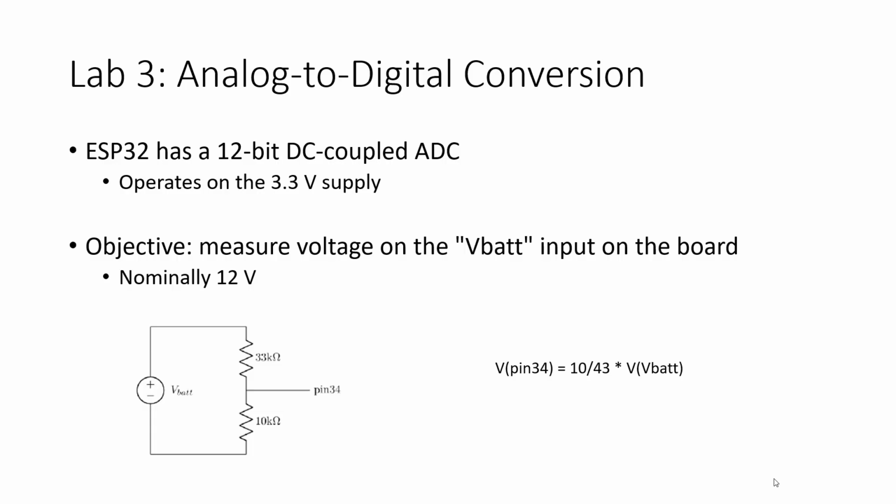The problem is that there's an issue. The purpose of the ADC in our case, and I think this is fairly common in projects involving this chip, is that you want to use this ADC to read the battery voltage. That's why it's DC coupled, right? I don't think the intent is to do software-defined radio. I think it would fail miserably at that task, right?